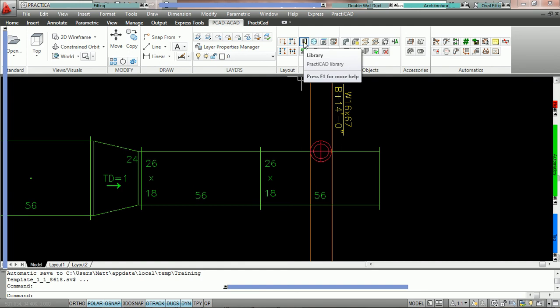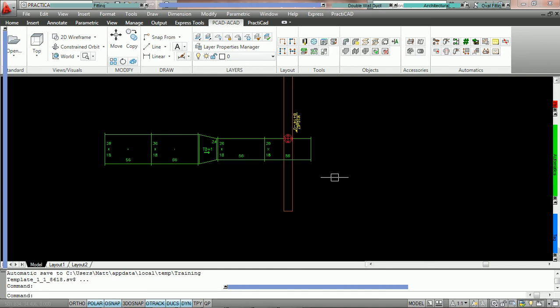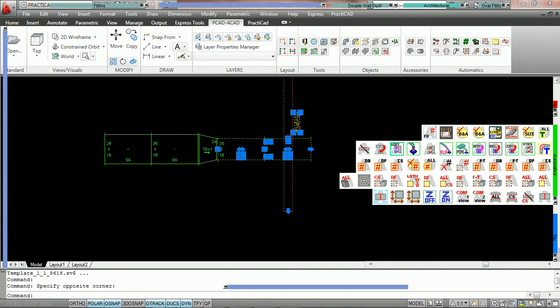So it's your choice to keep it on or off. Usually the reason you might turn it off would be the size of the drawing or your computer. Sometimes if you have a massive amount of collisions, it could slow down the system. So some users prefer to just highlight an area and run an automatic. But it is up to the individual user.